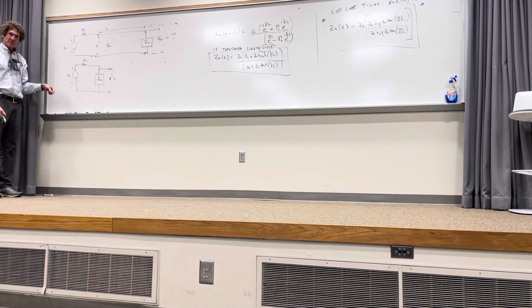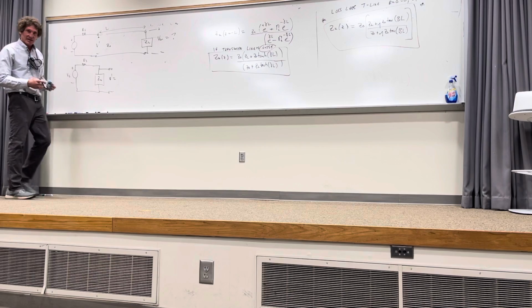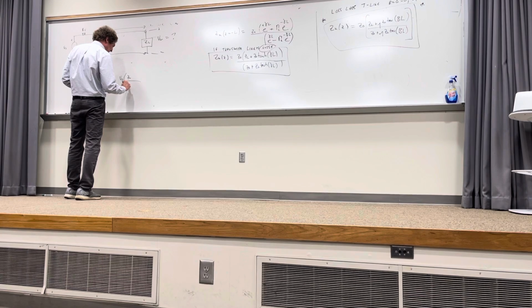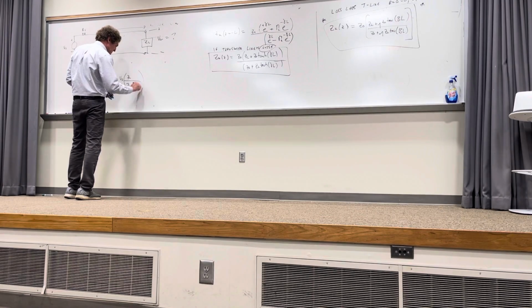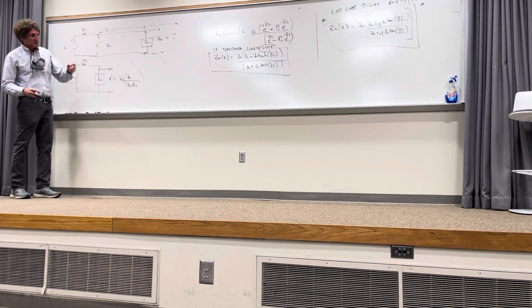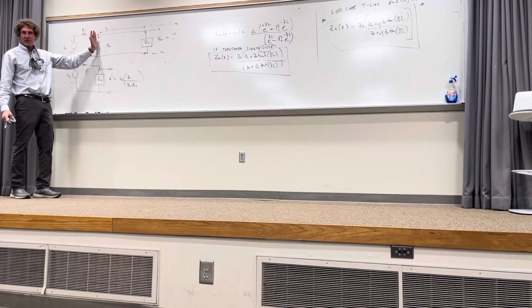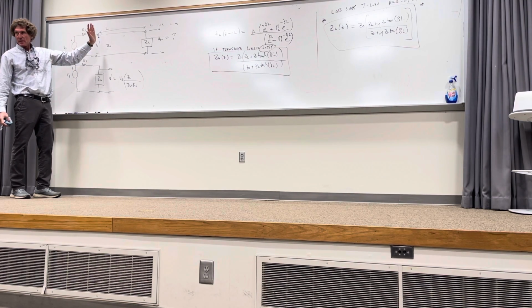Well, you could, but then when you multiply it by Zin, you're doing what I do. So you can say that V0 prime is really Vs, and it's times Zin over Zin plus, actually Rs, the source resistance. Now I didn't put Zin of L because I'm assuming the input can only be at L right here. Everybody all right with that?